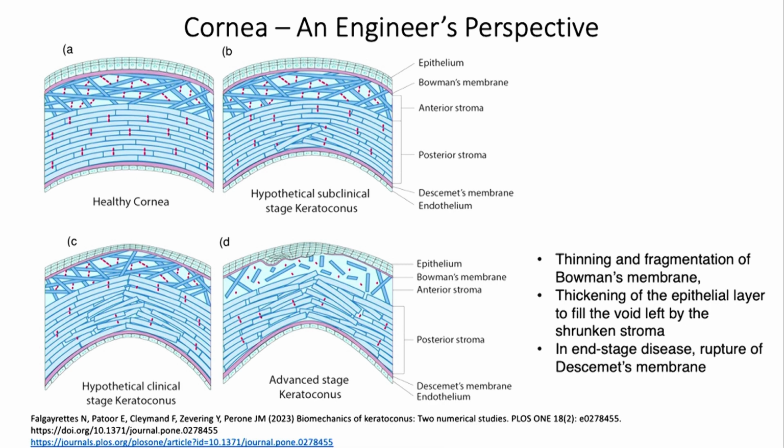So we do not know, when there is a disorganization of the collagen, how exactly the behavior changes. The problem with anisotropic hyperelastic is that there are a number of variables which define the behavior. There's not one like an E value. There are a number of them. Anisotropic means that in different directions, the stiffnesses are different for the material. So I have a number of parameters which define the behavior, and connecting the biological variations to the macro properties of the constitutive model is a key factor in understanding this disease.